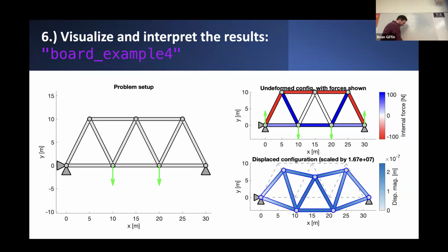Yeah. Ultimately, I think your rationalization in words is more or less what I'm going to reiterate in this pictorial representation. If we have only compressive forces along the top, but we're trying to figure out what these forces are here, the problem is we've said due to symmetry that they can't have opposing directions. So this is not allowed. They have to both point either up or down. But if they do that, then they can't be balanced by any external force. So that's just not admissible. The only way this joint could be in balance is if they're both zero. So zero force members there.